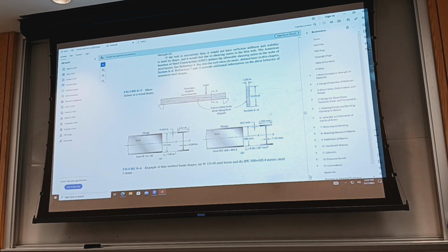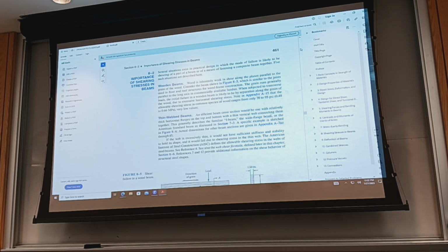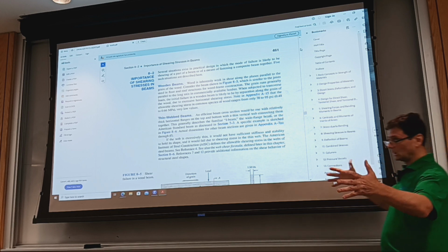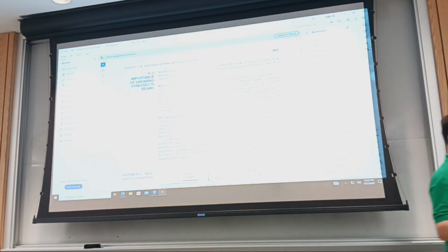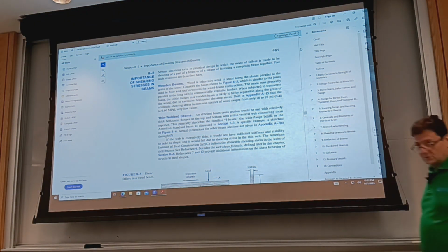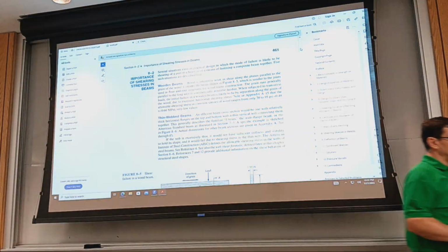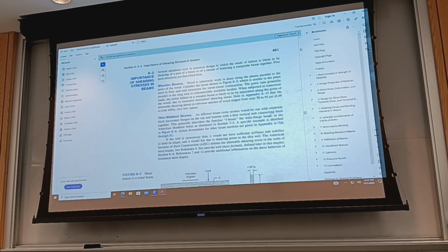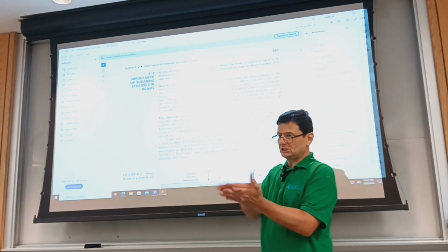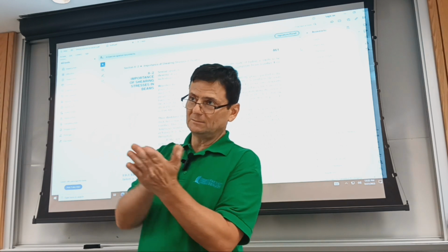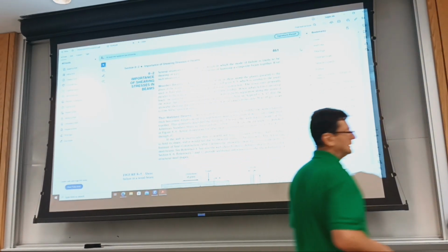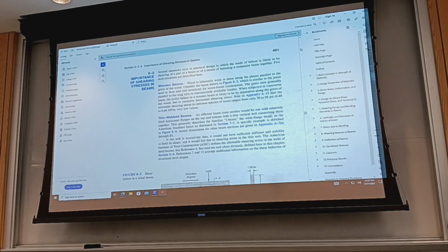So by the way, when are these types of problems important? I gave you an example with short beams, or analyzing stress in beams close to their supports. Moment is small, but you have shear stresses as severe as further in between supports. If you have wood, it is very weak when shearing the fibers. The longitudinal shearing stress of wood is pretty modest, if you look at the table at the back of the book.